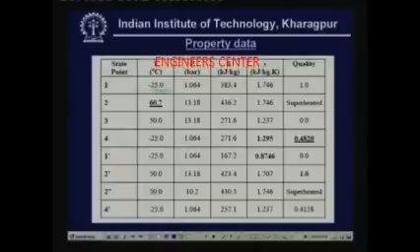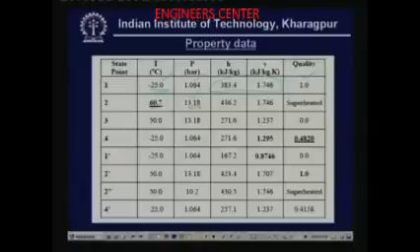This is the exit of the evaporator or inlet to the compressor. We know this temperature and quality, so we can find out the saturation pressure, and then we can find out the enthalpy and entropy from the pH chart or from the TS chart or from any other database. Next, point 2. Point 2 is the isentropic compression. We know the pressure, which is the saturation pressure corresponding to 50 degrees centigrade, and we also know that it is an isentropic process. So, the entropy is same. So, these two are known to us, so find the rest of the properties.